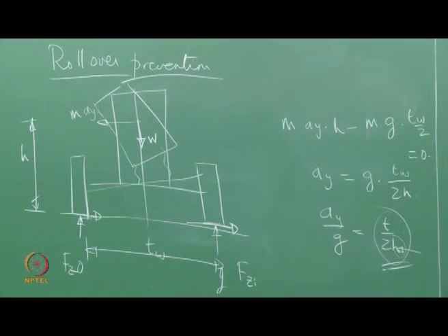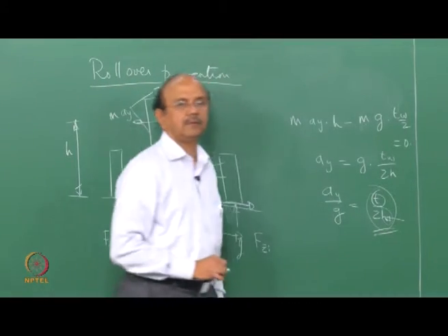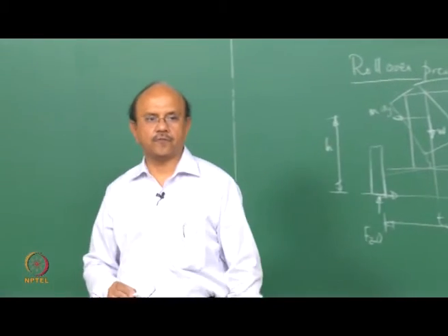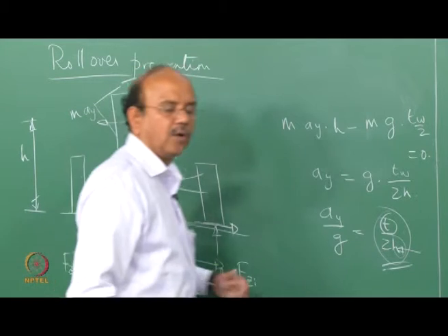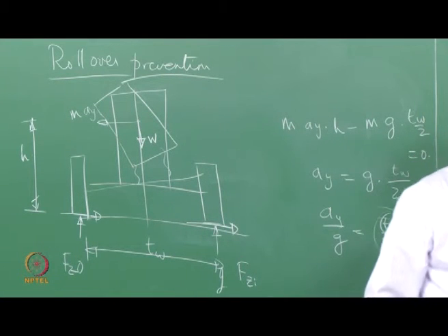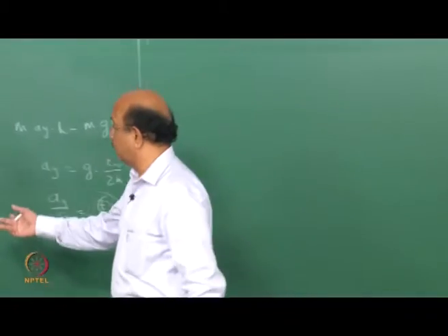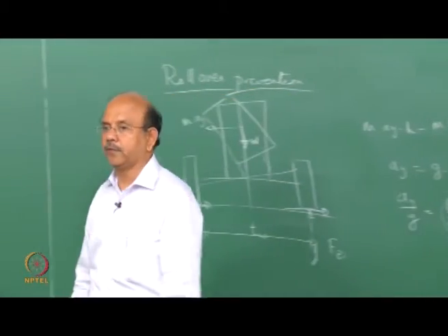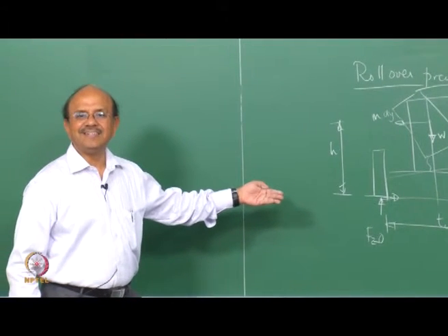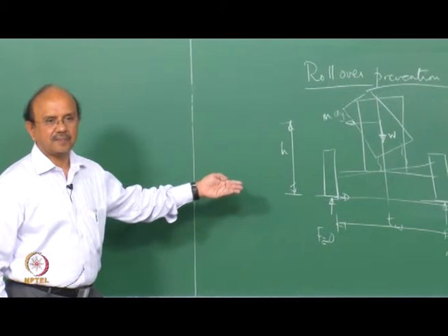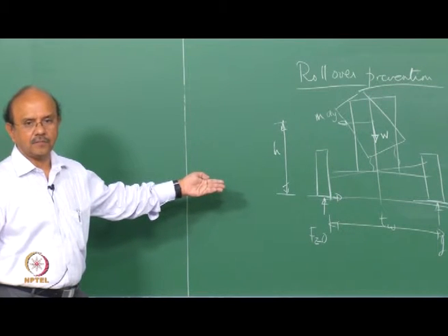So in other words, there are factors which affect T. T is affected by the kinematics and compliance of the suspension system. For example, even without going into the details of kinematics and compliance, it is affected straight away by the tire lateral stiffness.